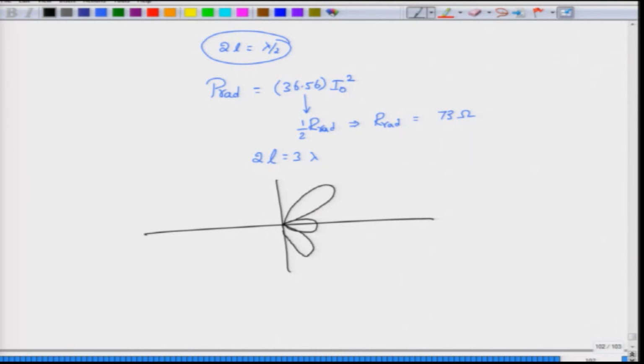I have only written for one third here, and on this side again you will find an antenna pattern that would look like this. So, this looks very colorful, or rather very beautiful, like a butterfly pattern, but consider the drawbacks of this antenna. Okay. The main drawback of this antenna is that you do not get only a single lobe, now you get 3 different lobes. Okay. Well, the energy is now being redirected or redistributed into multiple lobes.